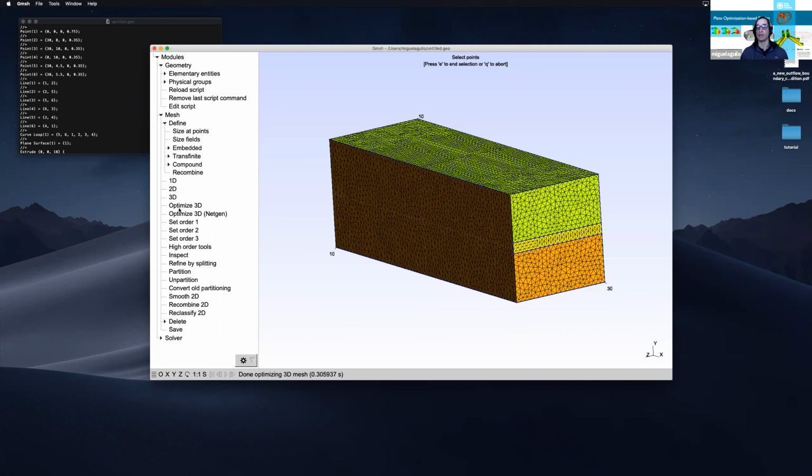So to answer your question, I know for sure they do tetrahedral elements. If you want a specific TET element that you want to use, then that depends more on the finite element code. In our case, we have support for linear TET elements, and we have another version that is a stabilized TET formulation that we use for plasticity problems as well as computational fluid dynamics.